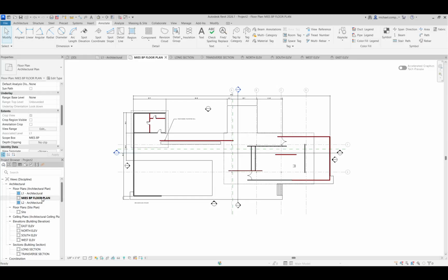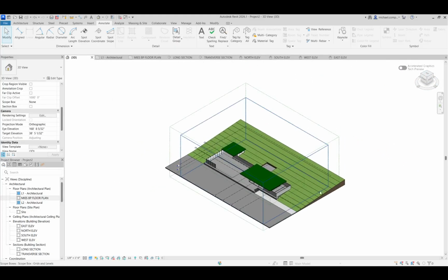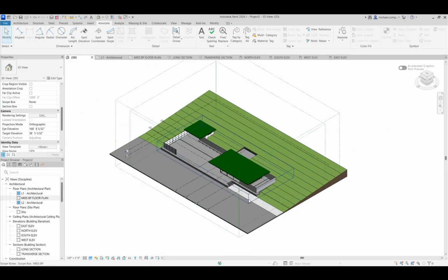The first thing I want to show you is the notion of a sectional axonometric view. And that's really easily achieved. If you go to a 3D view, any 3D view, and choose the preset corners of the box. So this is an axonometric view, right? Or isometric if you want to get technical, because the angles, I think, are similar. I think that's a 30, or actually, that might be a 30-45. I'm not quite sure. Or a 30-60, I mean. It doesn't really matter. But this is an axonometric view of the project.